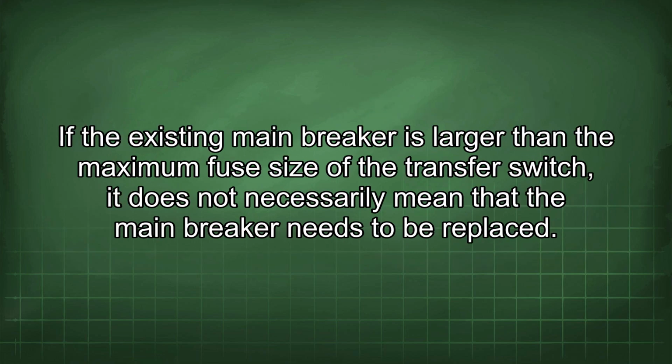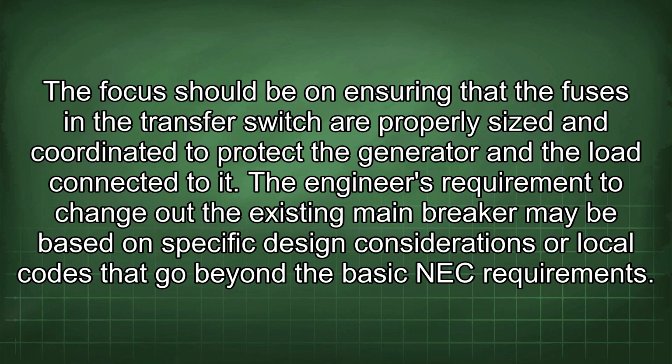If the existing main breaker is larger than the maximum fuse size of the transfer switch, it does not necessarily mean that the main breaker needs to be replaced. The focus should be on ensuring that the fuses in the transfer switch are properly sized and coordinated to protect the generator and the load connected to it. The engineer's requirement to change out the existing main breaker may be based on specific design considerations or local codes that go beyond the basic NEC requirements.